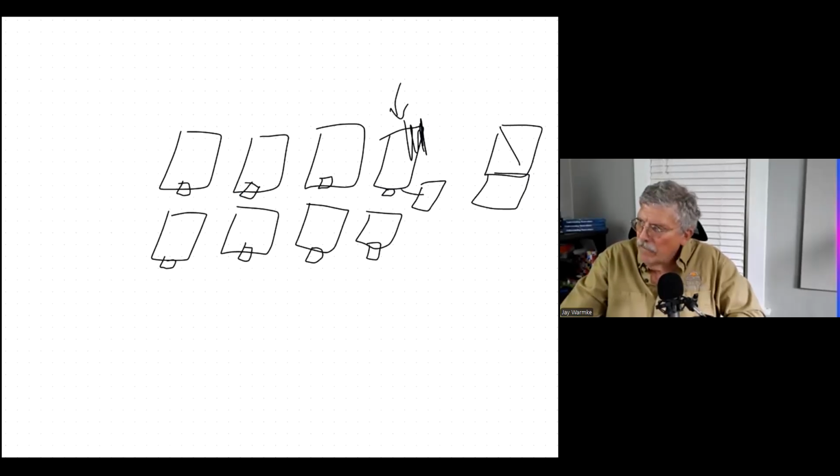Rather than combine them and only leave with one circuit, more often than not now we'll come in with both strings and we'll go into the inverter, and the inverter will have 2 MPPTs. So now this string behaves as a unit and that string behaves as a unit. So if this is shaded, it only affects half of the array, not the whole array. So we're not saving a little bit of wire here, but we are getting better output.